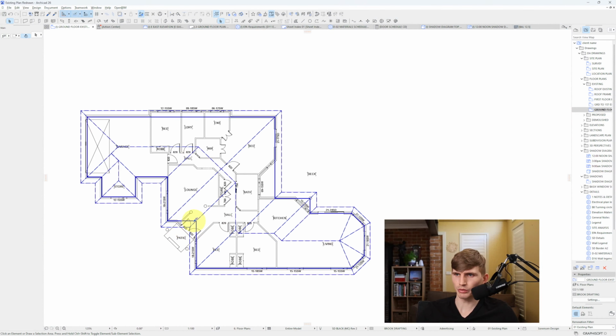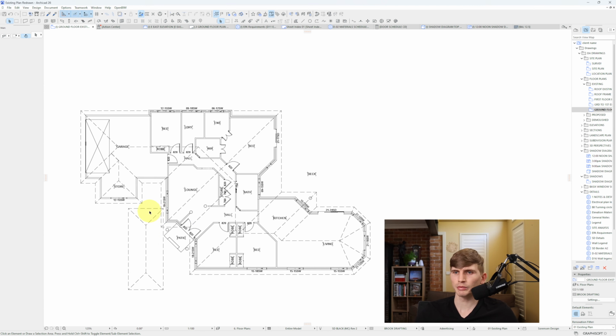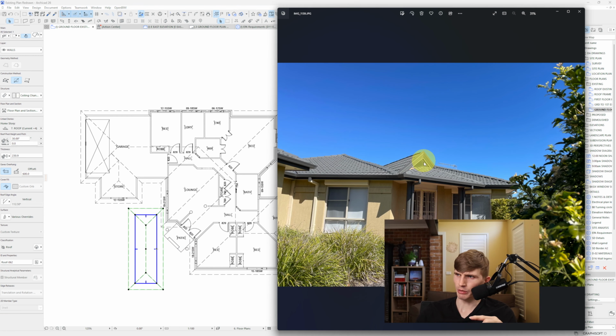All we need to do, we'll select our roof. With the multiplane method, we'll select this middle one just here, which is going to allow us to create more of a rectangle. This one just here, we'll tick it at about 2000 for the time being by say 6500. We're just creating a roof plane that we can essentially turn into a gable, just like this gable here.